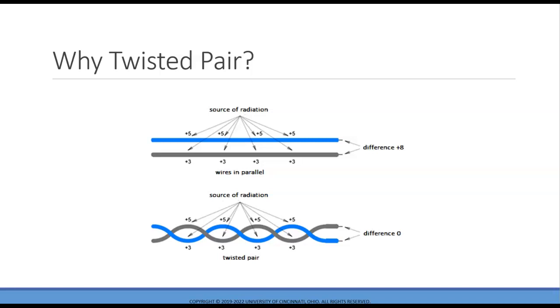Noise sources introduce signals into the wires by coupling of electric or magnetic fields and tend to couple to both wires equally. The noise thus produces a common mode signal which is canceled at the receiver when the difference signal is taken. Although it is immune to most background radiation, twisted pair wiring does not solve all problems. Twisted pair tends to have problems with strong electrical noise caused by close physical proximity to the source of noise, and it isn't effective against high frequencies used for communication.